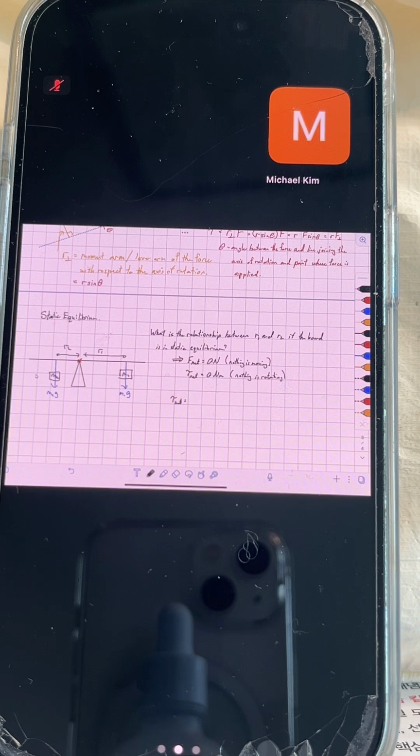And so we can see our net torque, if we make again the usual, we'll make this way positive, so counterclockwise positive, then M1 is generating a torque that wants to go clockwise relative to this axis of rotation. So I'm going to have minus the torque from 1 plus whatever the torque is from 2, and I know this has to be 0 Newton meters. Okay? And so this just tells me that the magnitudes of these two torques have to be the same.